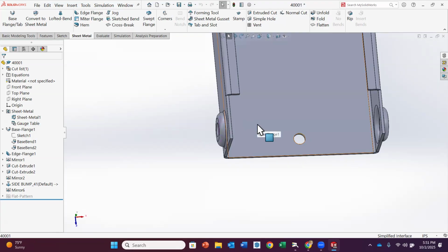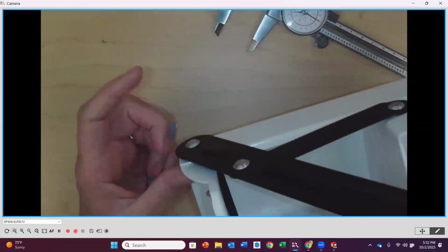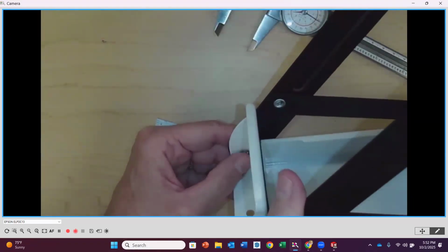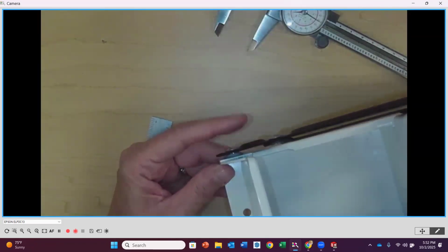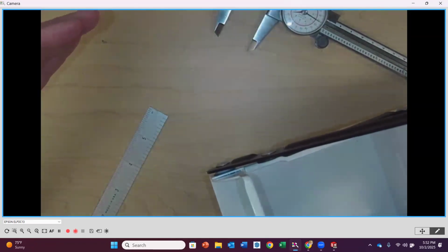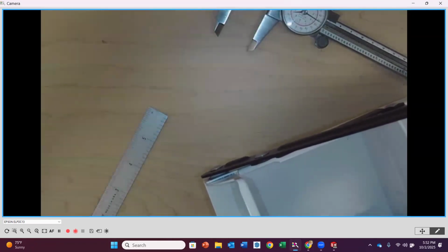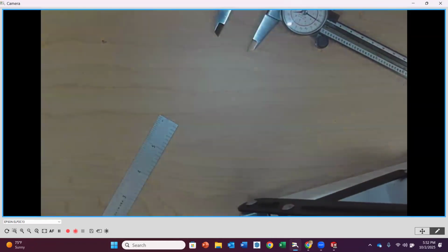This bump out, and I know it's not going to be easy to see underneath my camera here, but at the bottom, where our handle attaches, you can kind of see there's a raised dome. I don't see it here either because there's a part in the middle, but there's a raised dome there so that this handle is out from the side of that plate. So rather than putting in a shim or washers or something in there, they bumped that out, but you have to use a form tool to do that.